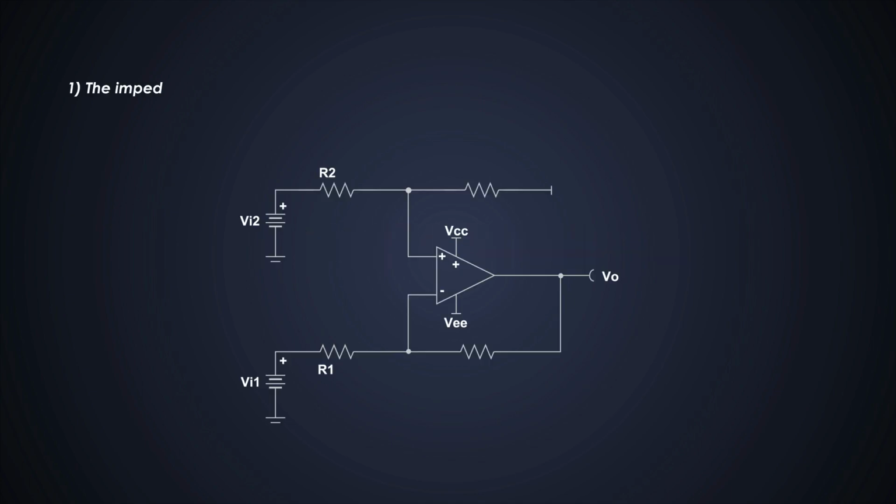First, the impedance of the inverting and non-inverting inputs are relatively low and unequal. Let's take our previous example. The input impedance to Vin is 10K, but for this Vin2, it will not be the same. Even though we add 10K at the non-inverting terminal, the impedance of Vin2 will be twice of that. So when voltage is applied to one input while grounding the other, different currents will flow depending on which input receives the applied voltage. And this unbalance in the source resistors will degrade the circuit's CMRR.